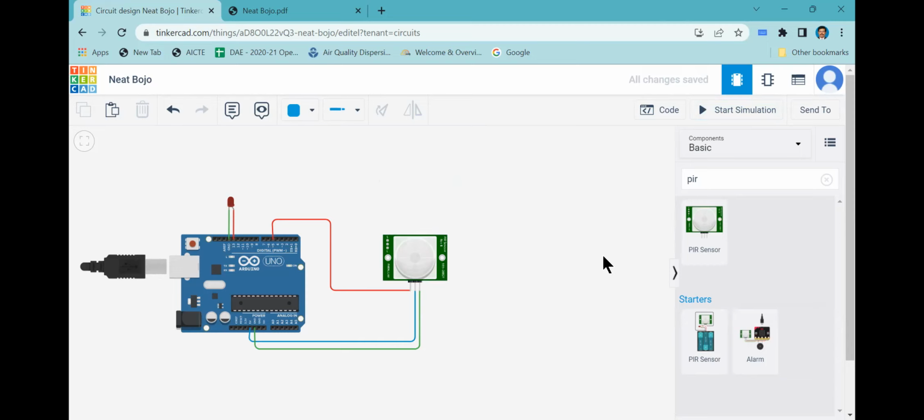See, you can actually do it in 12 also, there is no issue. And PIR sensor, again, there is one signal output. That means it is sending a signal of 1 when something is coming into a range. And one to the 5-volt power and then one to the ground.